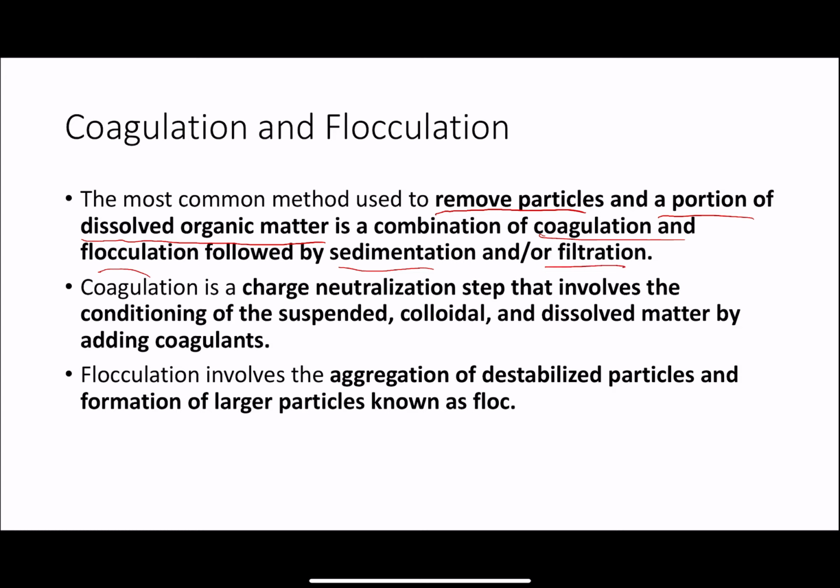Now, let's take each one of them as a simple definition. What is coagulation and what is flocculation? Coagulation, remember that most of the particles inside the solution have a negative charge. So coagulation is charge neutralization. We are trying to neutralize this negative charge.